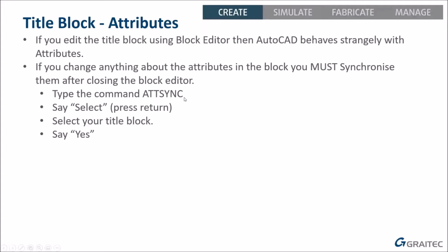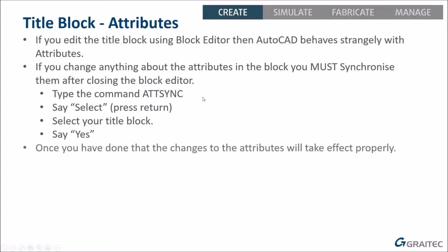It'll prompt you, do you want to select the block? And you say yes, select, or press return in other words, or the default. Then you actually pick your title block, and then it says, do you want to update it? You say yes, and then it's done. Not a lot of people seem to know this command, but it works perfectly well as long as you remember to do it. Once you've done that command, your attributes inside the block will be synchronized, so everything will be in the new positions with the new tokens and so on, and everything will work correctly. But that's really important.